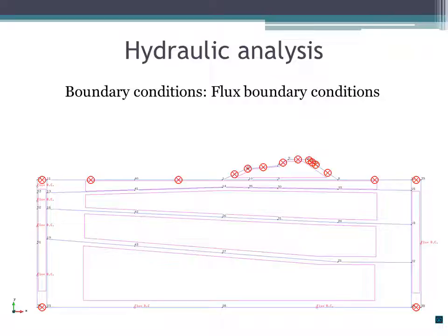The analyses have been performed with and without considering evaporation. In the analysis with evaporation, on the surface of the embankment a flux variable with time is applied, that is the net balance between the daily evaporation and rainfall. During the simulation of the flood, on the wet surface no boundary condition is applied because the water is activated and the line 6-8 becomes a part of the domain.